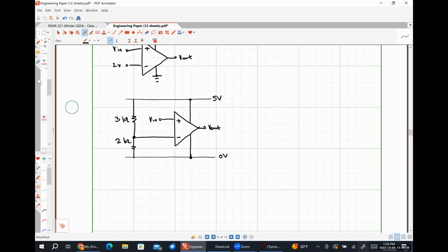So you chose to reconfigure the 10 and moved it into a delta. To go from a delta to a Y, you divide by 3. To go from a Y to a delta, you multiply by 3. So that should be 30. Yeah, okay. Also, take it as a delta, and then solve the Y. Yep.